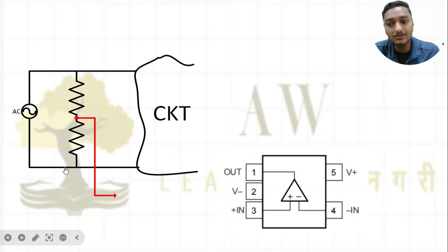But here in the case of AC, this is not 0, it will fluctuate. Let us say it is plus 230 volt AC RMS, then this particular leg, phase and neutral value, will be changing. Sometimes it is positive, sometimes it is negative, and that is why this leg is not stable, and its impact will happen here as well. And this IC has a common mode voltage of minus 0.1 to 3.4 volt. So that is the case.